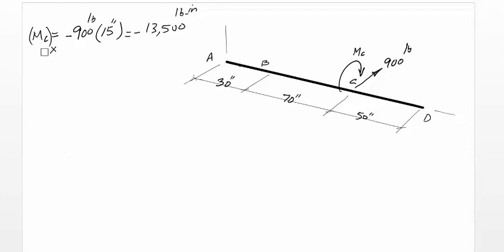At the same time, we have a force P, which is unknown, and also a moment about x-axis at B equal to MB. At A, we have three force reactions, AX, AY, and AZ. At D, we have DY, DZ, and no DX because it has no axial thrust.